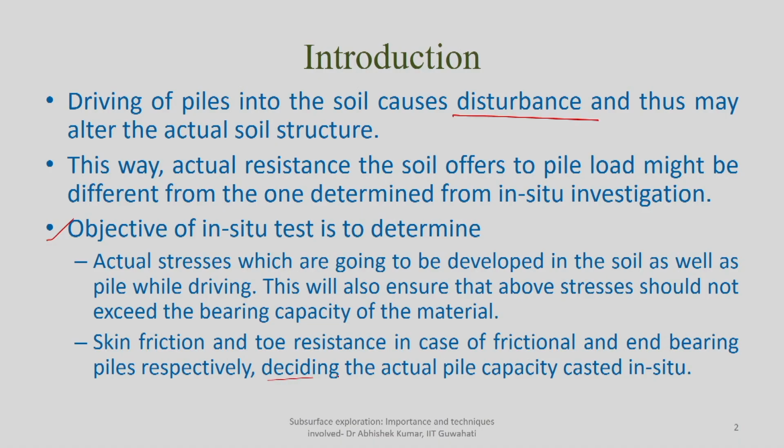Second, the skin friction developed as a result of the different layers available along the shaft of the pile, as well as the toe resistance based on the soil property available at the base of the pile, whether they are offering sufficient resistance taking into account your design consideration. This will also help in deciding how closely the actual pile capacity, cast in situ, matches your design parameters and design consideration.